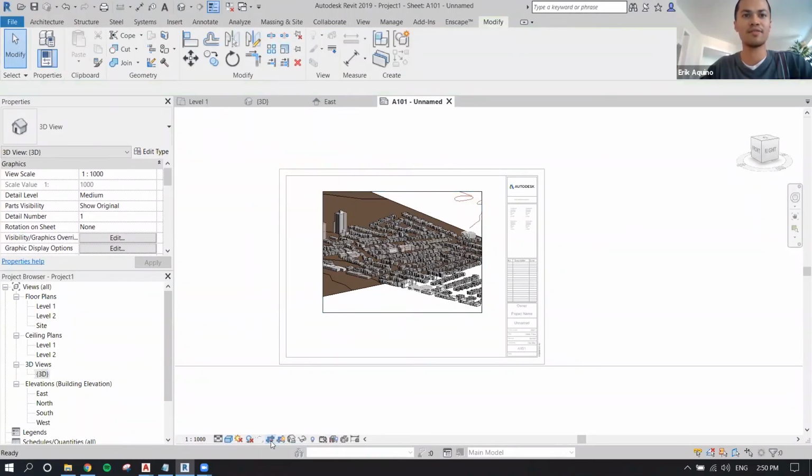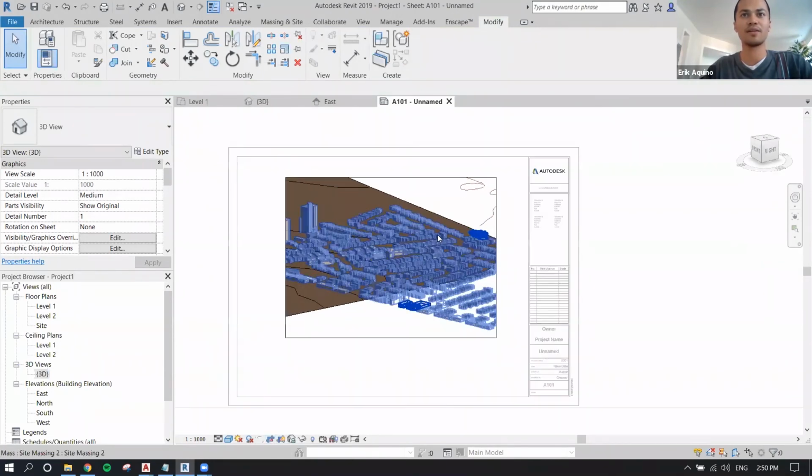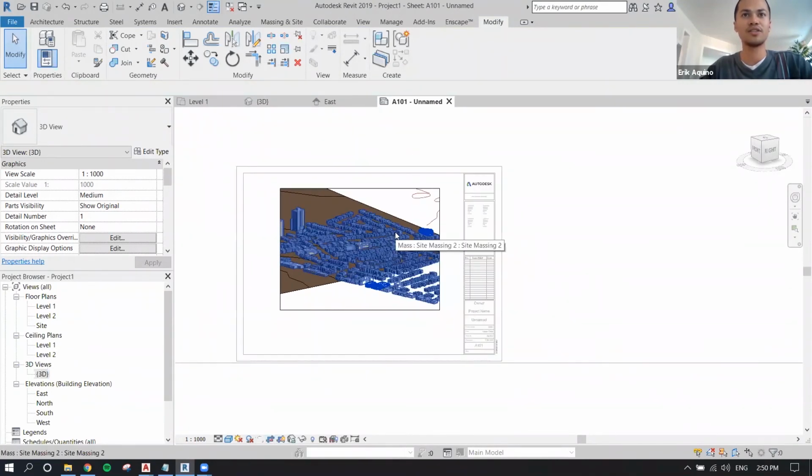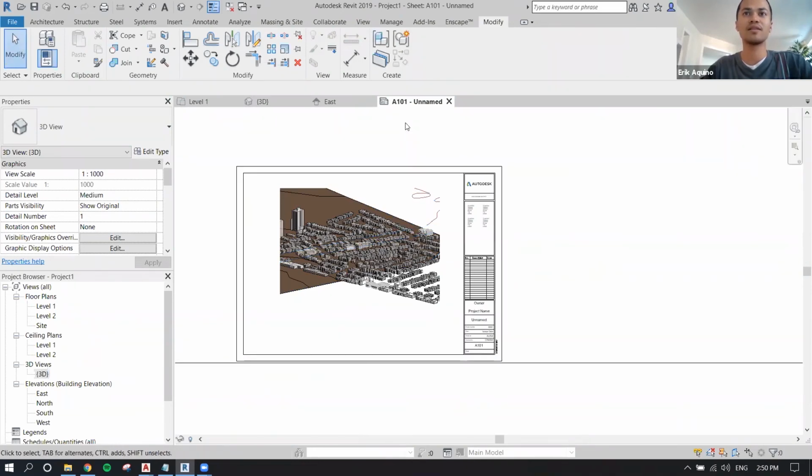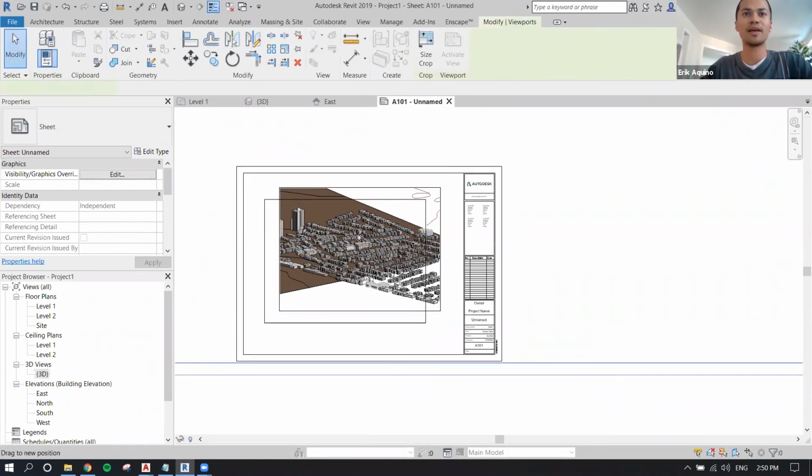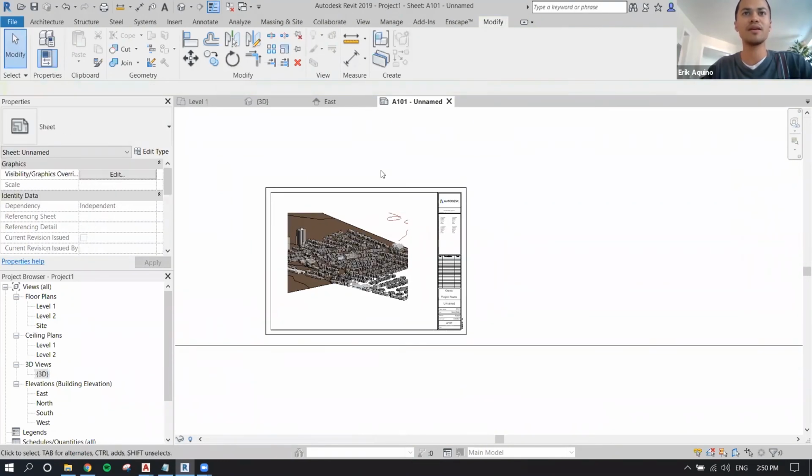If I have the X toggled off, that would be our view on our sheet and also in our working view. So you're making changes not only in the sheet, but also to the view. Here I could toggle off whether this border is shown, double click outside. Otherwise you're still working inside this view. And then from there you could print the sheet.